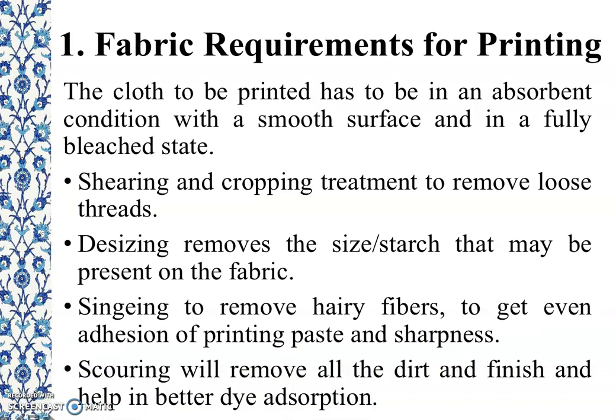Better quality of print and clarity of color can be achieved if fabric is pre-treated so that it improves the absorbent condition with a smooth surface. The pre-treatments are shearing and cropping to remove loose threads, desizing to remove the size starch that may be present on the fabric for proper penetration of printing paste, singeing to remove hairy fibers to give even addition of printing paste and sharpness.